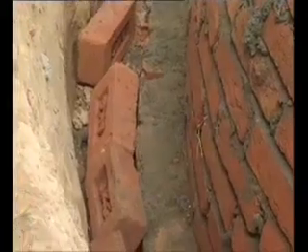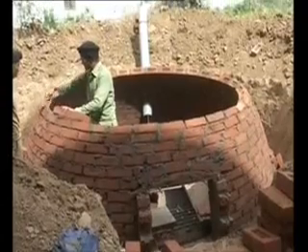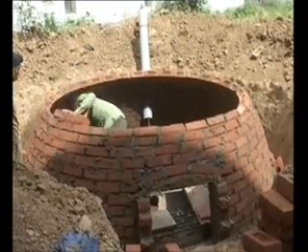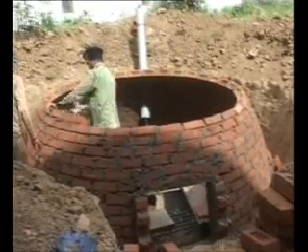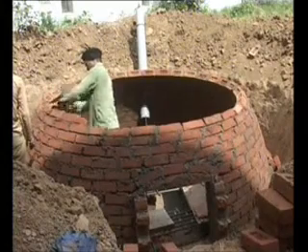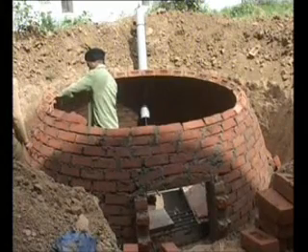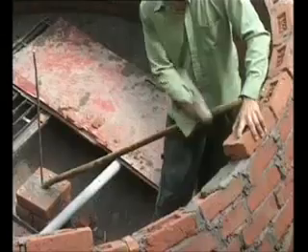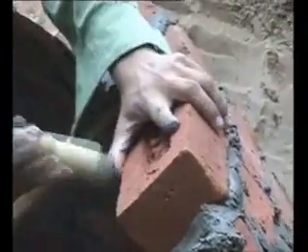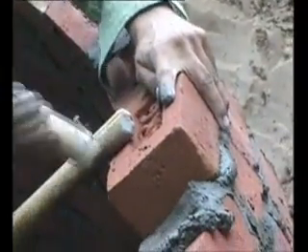First layer of bricks is laid on the foundation of the digester, which is 9 inches thick. Further bricks are laid in 4-inch size. By the construction of the 4-inch size wall, gradually an arc is developed and construction goes one by one till the top. In order to keep the radius constant, we always measure the radius with the help of a stick.